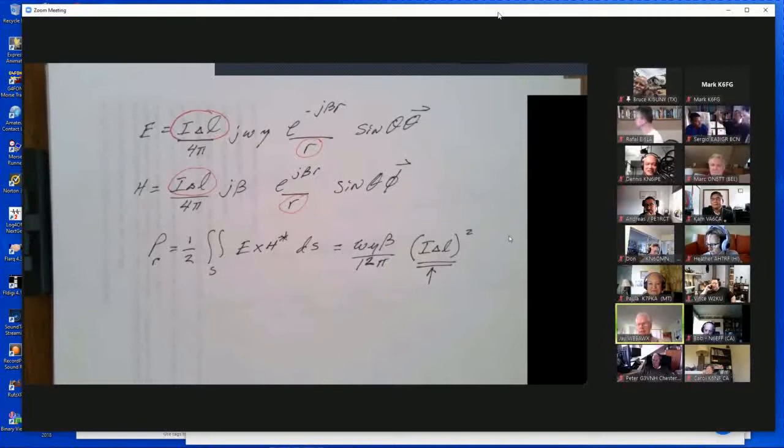Anyway, what they did was invent this idea of a magnetic loop, because it has no voltage nodes. It doesn't have the high voltage on the tips. Their dipole was literally getting shorter because it was burning off the tips. So they made a magnetic loop. The magnetic loop is a good antenna. It just has to be a little bit bigger if you can do it. And you might look at your matching network. You might need more than just a series capacitor.